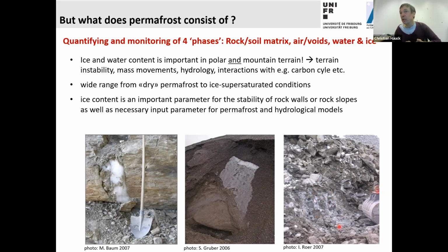So it's not a debris covered glacier. You see this rock ice mixture also below the active layer. This is buried snow here, and this would be ice, so buried snow that has been transferred to ice. Also, this is permafrost. So geophysically speaking, as you can imagine, we'll get completely different responses from our geophysical surveys when we are measuring on top of this.